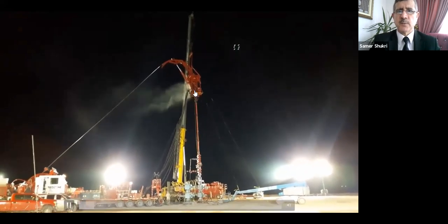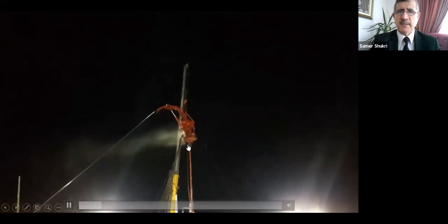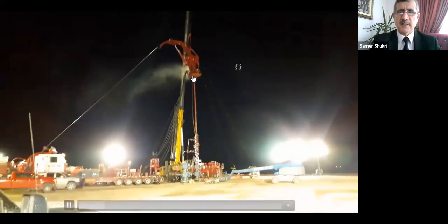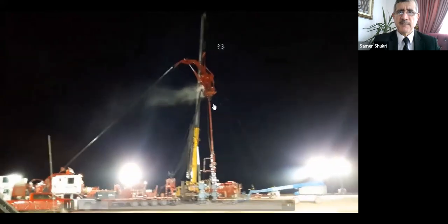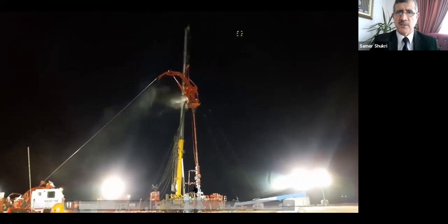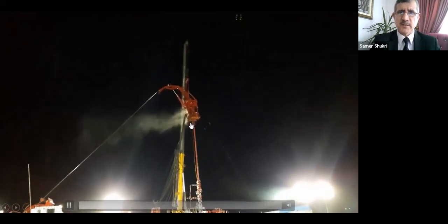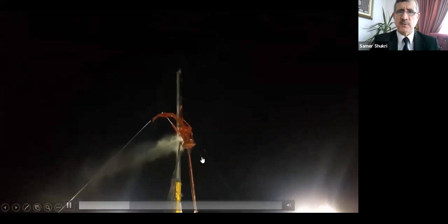Then we inflow test the BOP. If it is okay, we can replace this stripper and make it safe. Then open the BOP after equalizing the pressure. We do a pressure test in this section and ensure that the new stripper is holding pressure. After that, we can continue our operation.